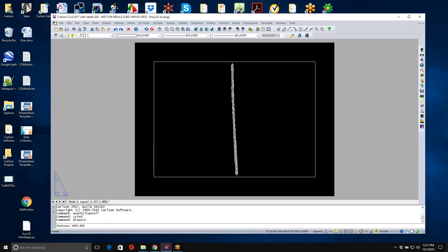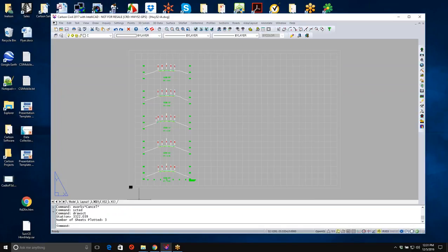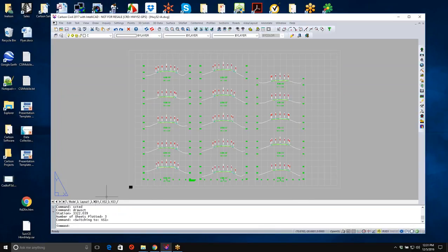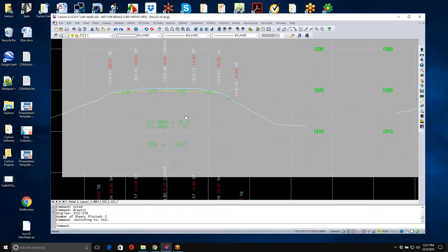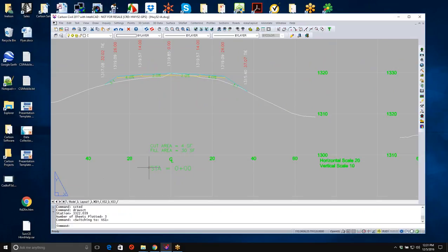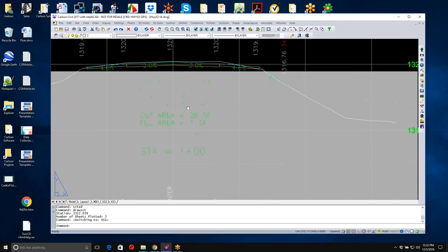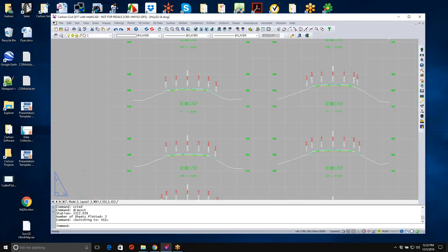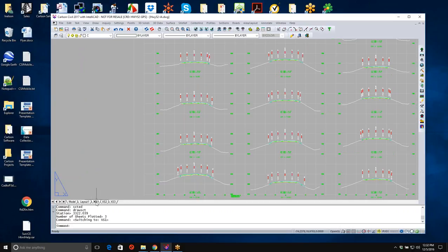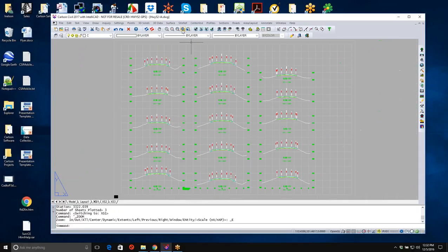And then we will have the cross-section sheets being built, and I've got 3 of them that are in here. So if we take a look at this in cross-section sheet number 1, you can see that I've labeled the sections to start in from the sheet, and so what we'll have in here are the offset values listed here on a per grid basis, the end areas that are established for me, and again here's where we can see we have the different offsets and elevations, and then feature codes for labeling and even for stakeout purposes. So we've also annotated in each of the end areas in here for each of these particular sections, and at this point it's just a matter then of telling the software it's time to plot.